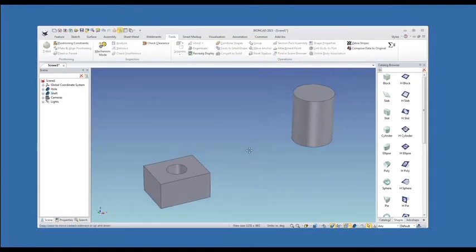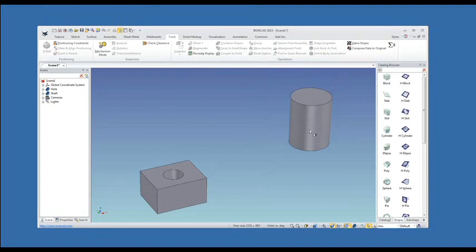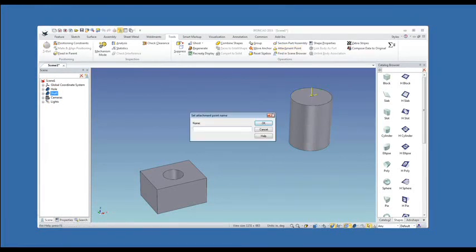So now we've got our parameters in place, but we need to add our smart attachment points. So we'll grab a regular attachment point and place it there, and we'll set the name. And this time we want to do our 1_n, but then we're going to open parentheses here and do a colon. In this format you might have to watch the video a few times, and we want the shaft radius to equal the hole radius. So that format's pretty straightforward, but remembering this syntax, it's in the help, but you can watch the video a few times before you memorize that.